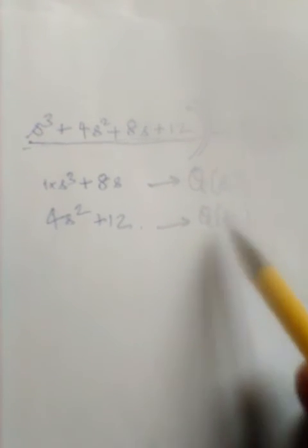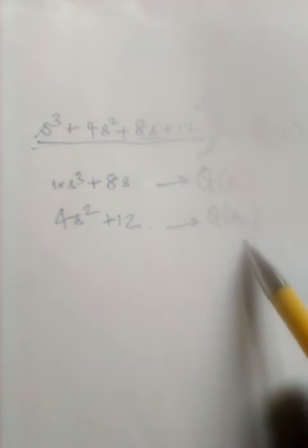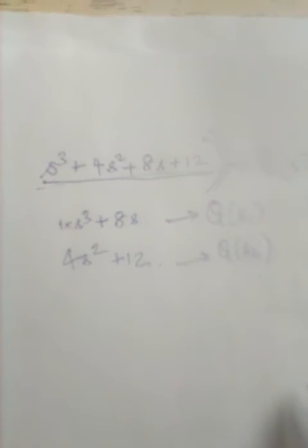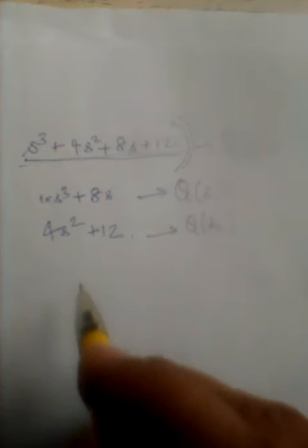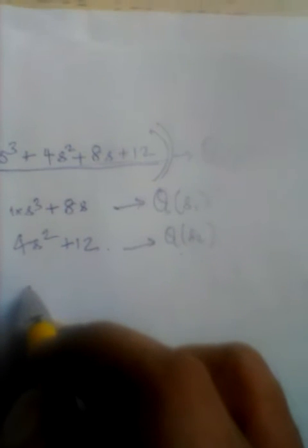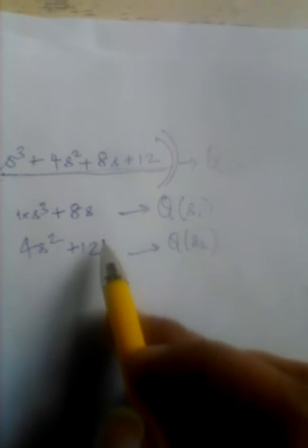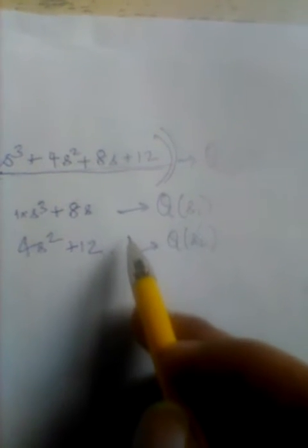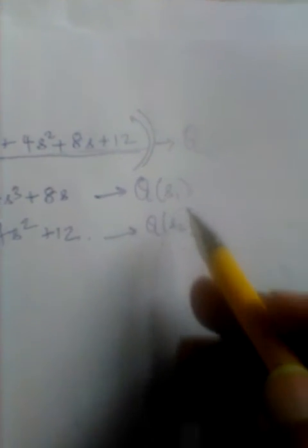And then from these functions, I am going to derive some other method such that I determine the stability condition for this particular polynomial associated to the characteristic equation. So how can I do that? I want to take the highest. I have the first polynomial which has got the highest degree. Here it is a 3. So I can divide the first polynomial by the second polynomial.